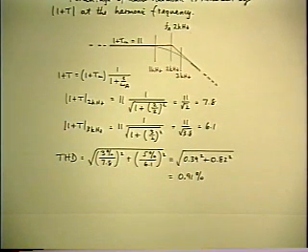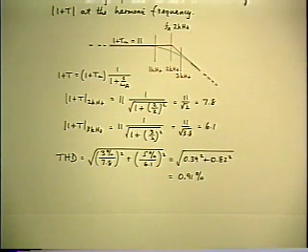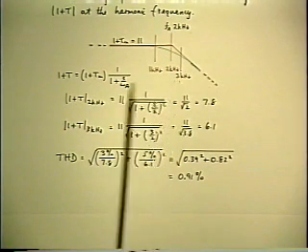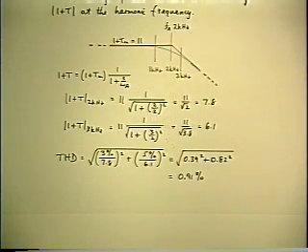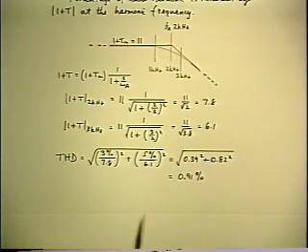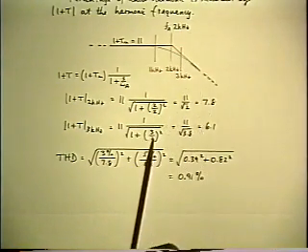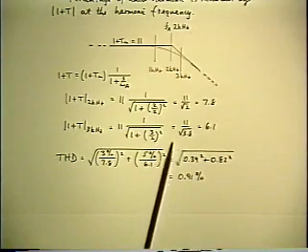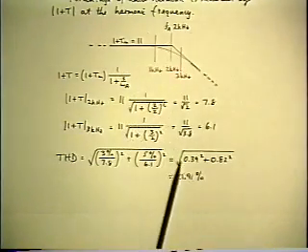And once again, notice that in spite of the fact that the closed-loop gain bandwidth is flat from 2.7 hertz to 22 kilohertz, it's still a crummy little amplifier. Because not only does the output impedance rise outside the much narrower mid-band range for TM, but the distortion reduction factors also decline outside the same narrow range.